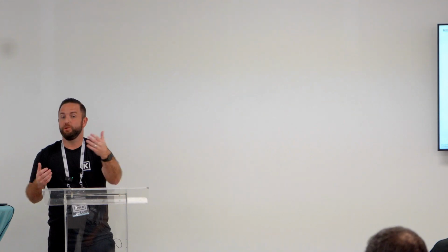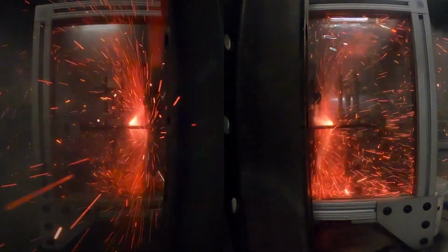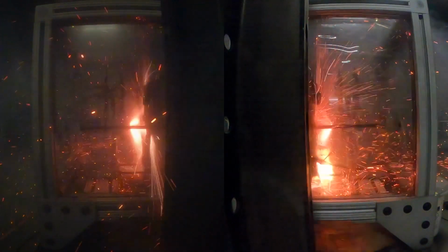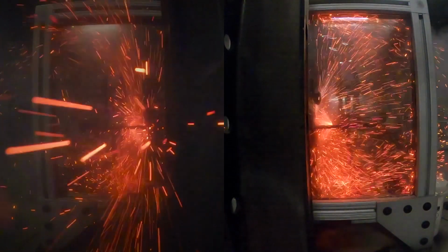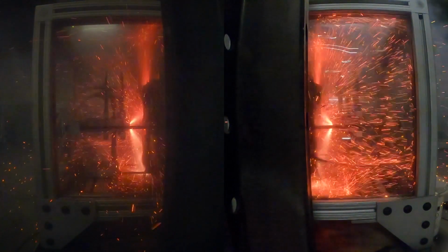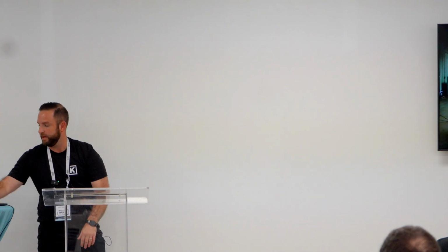The point is, you use one of those methods. I could just as easily throw a heater video up. I could just as easily throw an overcharge video up and show you the voltage, the current pumped into the cell, and then boom, it goes. But the point is, you follow one of these triggering methods, the cell is going to go into thermal runaway, and then we've got that to deal with, right? Backing that up, we can design for all those failure modes, but we can't design for the internal defect. So we have to have designs that deal with that.